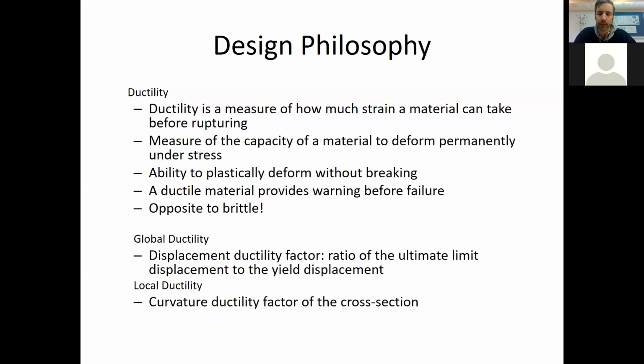If you have a beam made of steel and you bend it out of shape, well, it actually goes out of shape, but it doesn't break. It doesn't break off. At least not with construction steel. Of course, there are some kinds of steel that are very brittle. The kind of steels used for tools, for example, is much more brittle. But construction steel is ductile, and it has this ability to plastically deform without breaking.